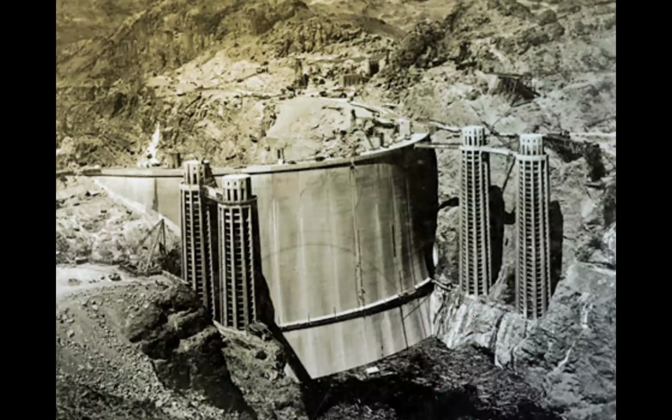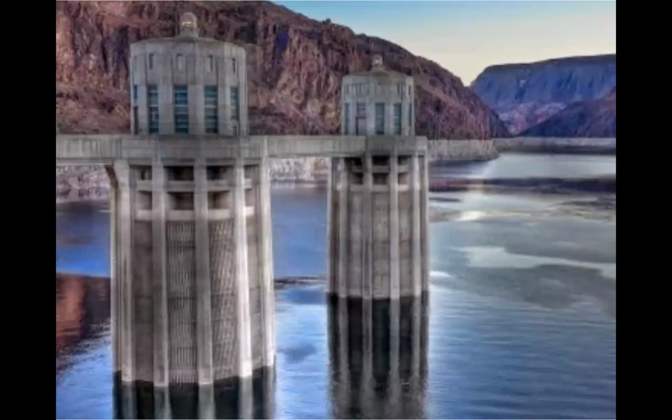This one's another example. It might be Hoover Dam, I think, but I might need to confirm. But again, the 4 intake towers on either side are basically selective withdrawal type features. This is another example. Most of them, you see, have a trash rack. That's what is used to keep out debris and trash. And sometimes there are big trees coming down or different things, so you want to keep them out. That's why they have that. Not in this case, but sometimes you have screens to keep fish away, that kind of application.